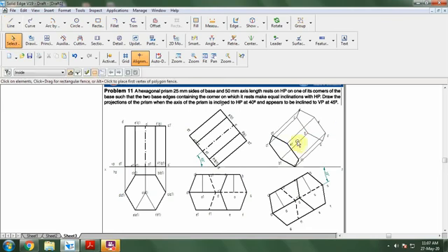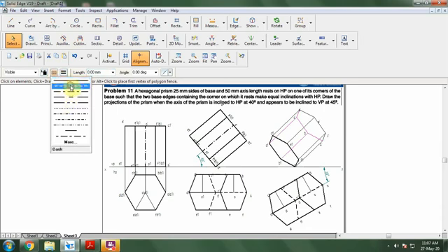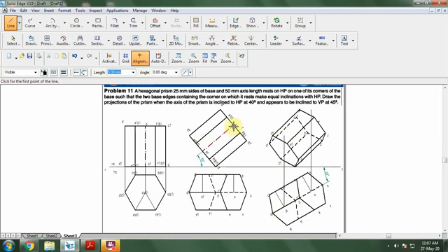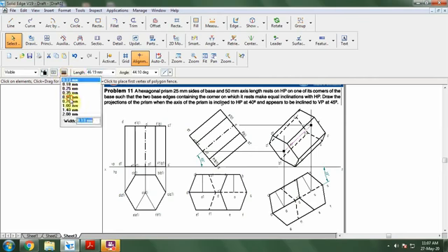I want to select that 1, 2, this, and this. I want to make as dotted line. So remaining all the lines will be visible. Select all the lines and make that as 0.5 mm. To draw thickness, I want to take the axis, that is O and O1. From here again, this will be having O point and this will be having O1 point. Join that, select that and make that as an axis line with 0.5 mm thick.